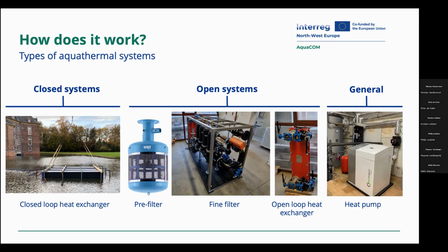They are made out of titanium because the water can have corrosive properties, and to avoid corrosion in the installation we have to use the most noble materials, to avoid corrosion somewhere in the installation, and also, of course, leakages. So it's a very critical part in the installation and needs to be protected as much as we can.